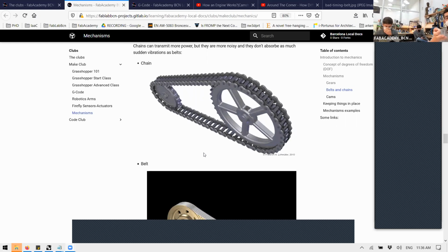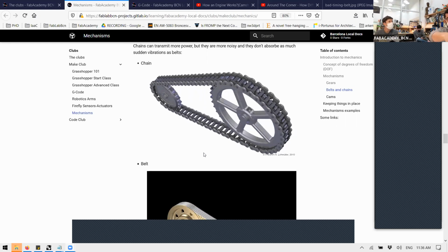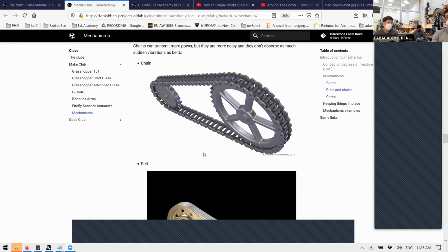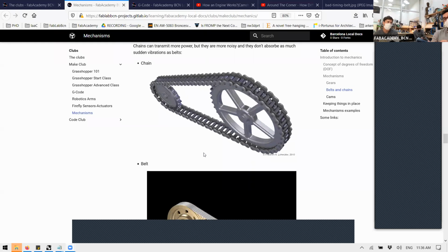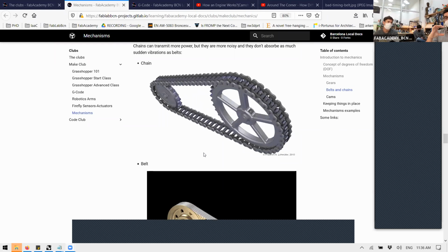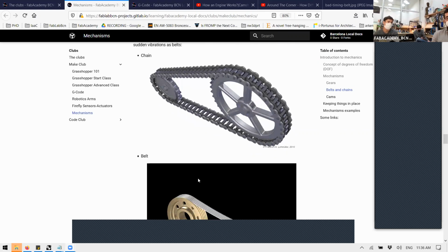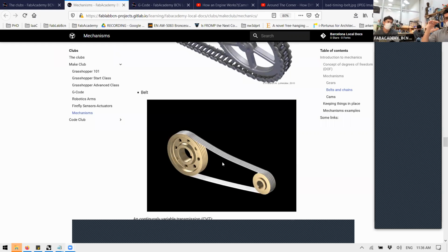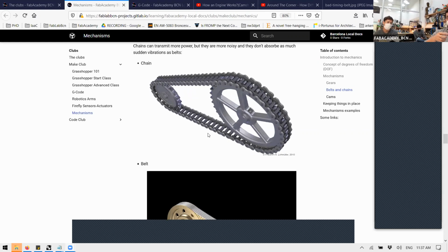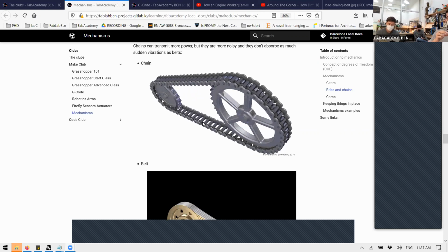For example, to give you an idea, I know because I've been looking a lot into this this week: chains in a bicycle last around 10,000 kilometers. Belts, 30,000 with no maintenance. What determines the belt's life is the length and how the rubber gets worn. Usually you have a mechanism to increase the tension, like a third wheel, to slowly accommodate the elongation. The same happens with chains. Chains also elongate because the bearings inside the little knobs get worn, but they have higher maintenance.